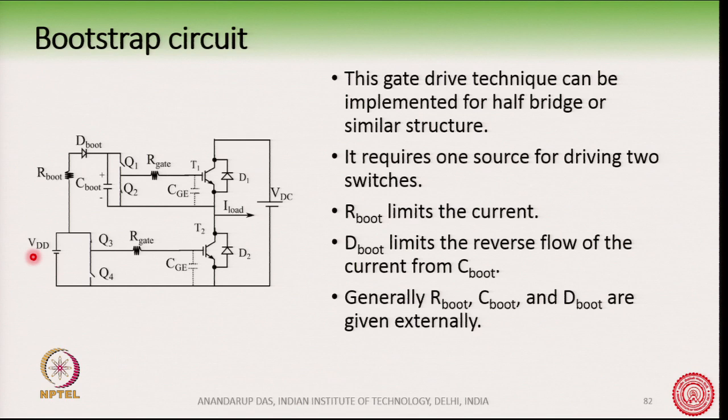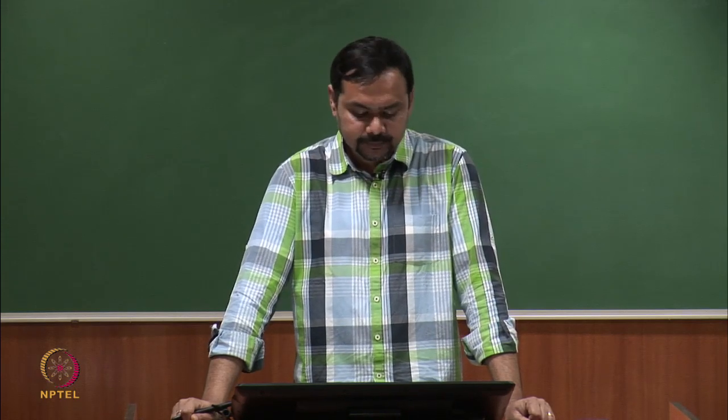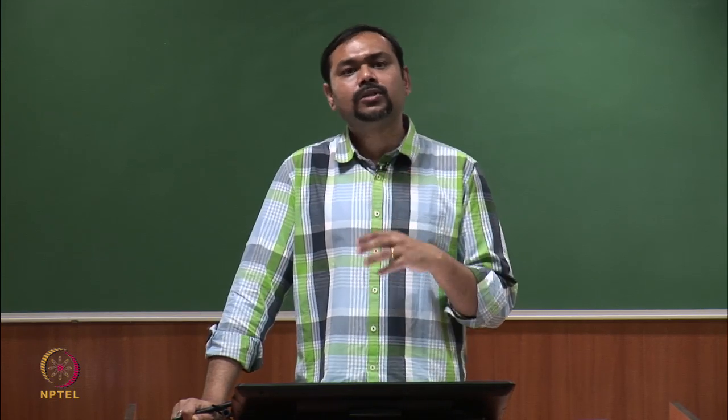So, now we will talk about bootstrap circuits. Often we see, for example, for this kind of voltage source converter, we drive half bridges, and we have seen that we can use gate driver boards for each IGBT, one driver for the upper high side IGBT and another driver for the low side IGBT.